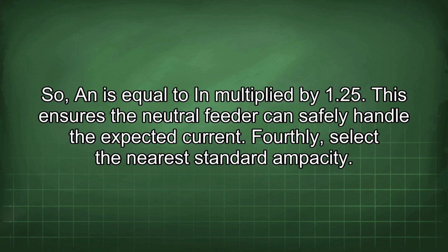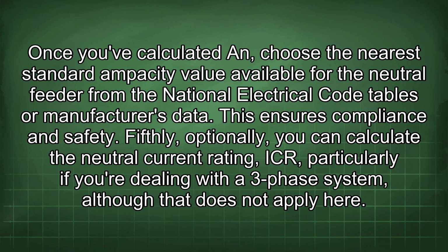Fourthly, select the nearest standard ampacity. Once you've calculated IN, choose the nearest standard ampacity value available for the neutral feeder from the National Electrical Code tables or manufacturer's data. This ensures compliance and safety.